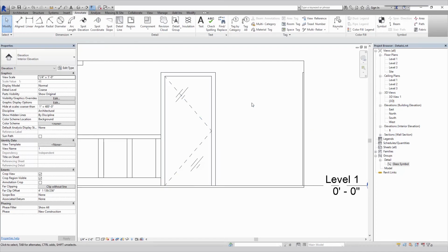As usual in Revit, there are multiple ways of doing the same thing. You can choose, like I said, to do this as a group, or you can create a detail component, or you could even create a symbol right here. So choose what works best for you as you detail and as you generate your project details.